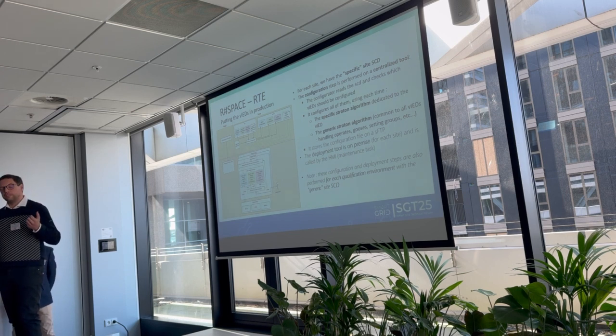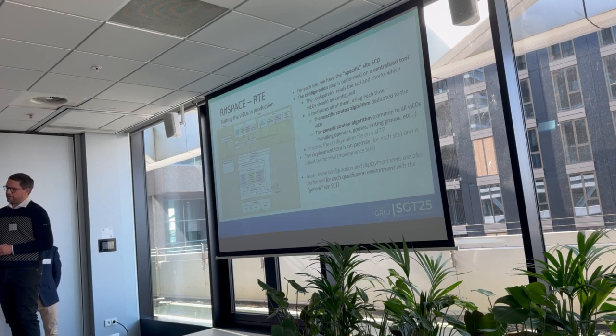So this SCD is produced at RTE, by a tool we developed in-house. Some colleagues have developed the software to generate our SCDs. And once we have these SCDs, we take them into our configuration tool. This configuration tool has also been developed internally by RTE. And this configurator basically reads the SCD, and it will see if there are virtual IEDs, if there is a gateway, if there is the SCADA, and it will configure all of them automatically.